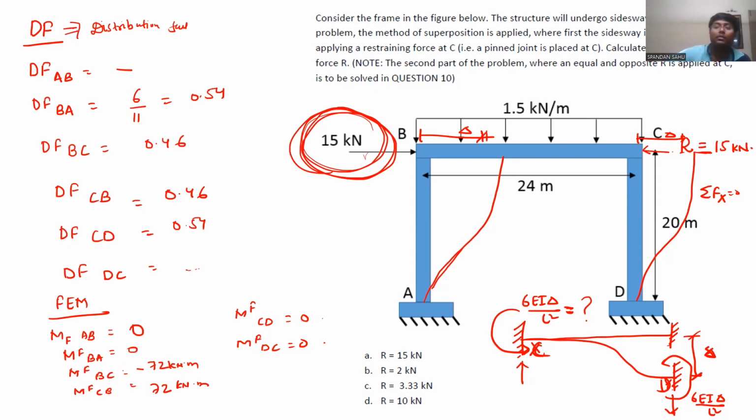In the slope deflection equation, we need to calculate theta B. That is the way you can find delta. From here you cannot find it, because you need equations, right? You need to generate equations. Here we are not generating any equation in moment distribution. That is the beauty of moment distribution; you are not solving any equation. But to determine your unknown, you need to write an equation. Without an equation, how can you solve your unknown? Correct or not? Okay, sir.